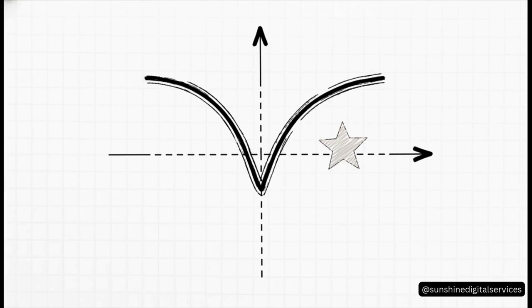So, did it work? This is the moment of truth. The simulation spits out this graph, and what we're looking for is that deep dip right in the middle of the plot. And there it is. That sharp V shape tells us that our antenna is resonating perfectly. It's efficiently taking the signal we fed it and launching it as a radio wave right around our target of 2.4 gigahertz. It works. That's a successful design.